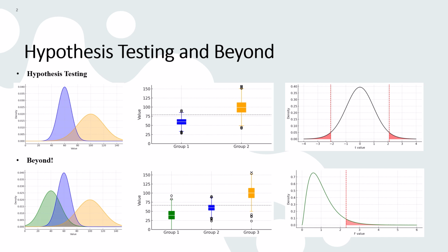become essential. Design of experiments helps us plan experiments efficiently, allowing us to test multiple factors, like temperature, speed, or pressure, at the same time, rather than changing one at a time. This saves time and resources and helps you understand interactions between variables. ANOVA is the statistical tool that helps us analyze the results. It tells us whether the differences in group means are real or just due to random noise.